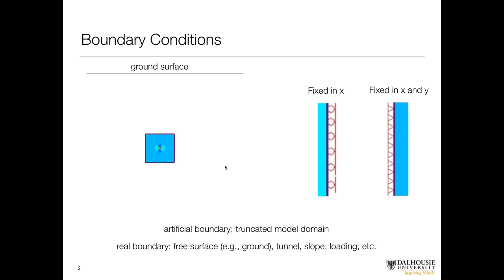So there's many types of boundary conditions. There's deformation boundary conditions, load boundary conditions, and free boundary conditions. Here's a couple of them over here to the right of the most common ones. Right here we have a boundary condition called roller boundaries. See these circles? In this case, that means that the model is fixed in X. Each one of these circles represents a node. The model is free to move up and down in Y, but is fixed in X.